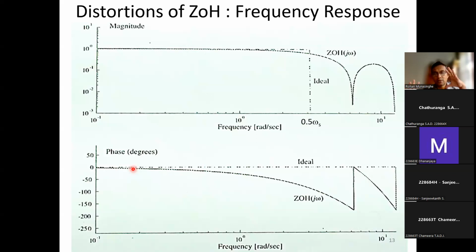That is the only reason. And if you have sufficiently capable hardware to handle all this high frequency sampling, you can exercise it without any problem. And the other thing is, once you achieve a certain amount of accuracy, you need not look for any further accuracy, as I already explained before the break, right? You can figure out what sort of delay you can exercise. Say, for example, you have 45-degree phase margin, and you can go down to about 35, right? Without any harm. So which means you have 10 degrees as your phase loss.